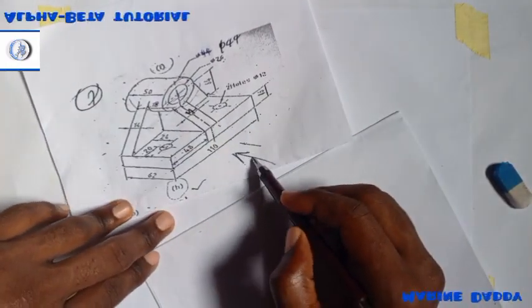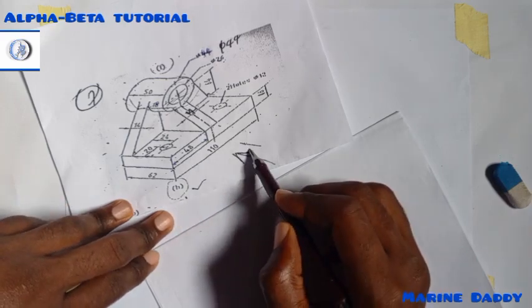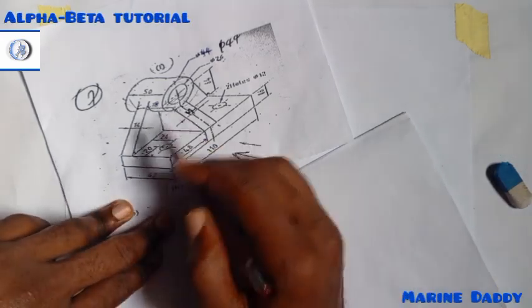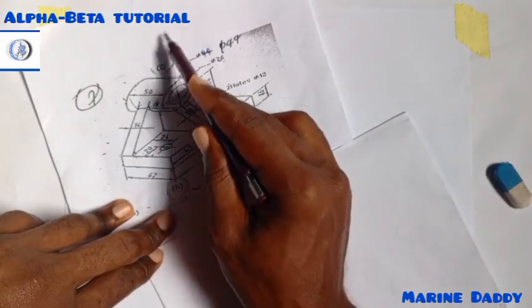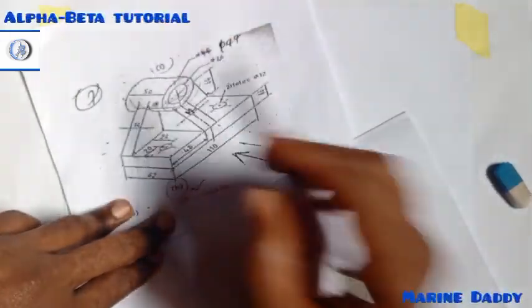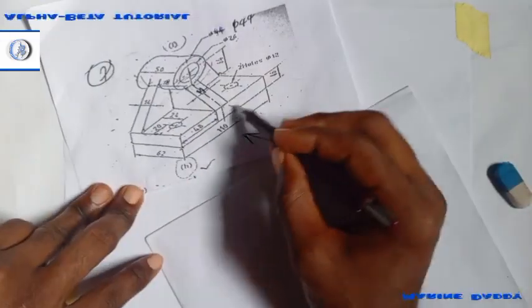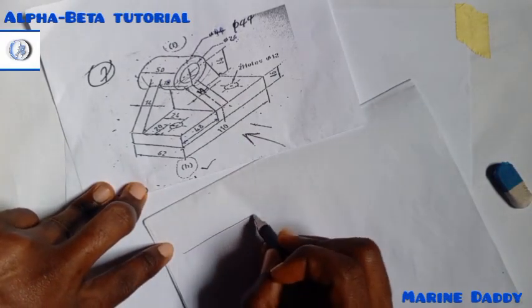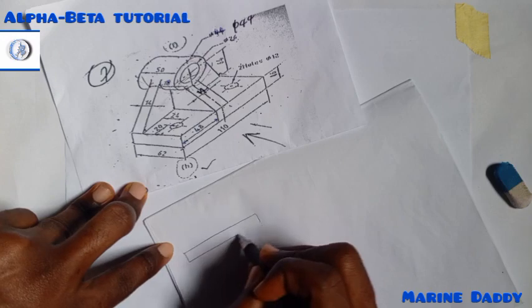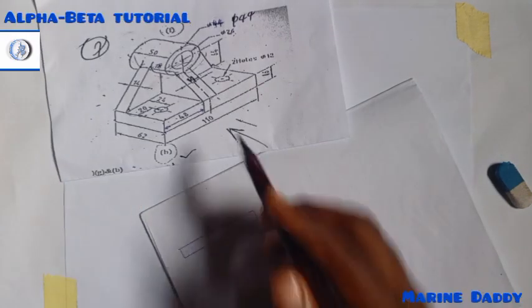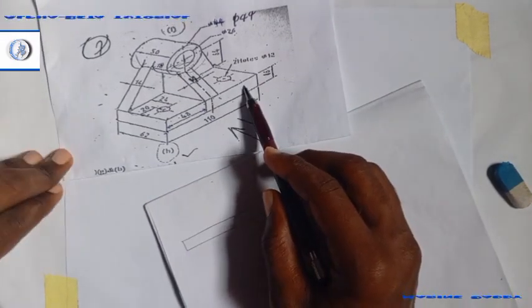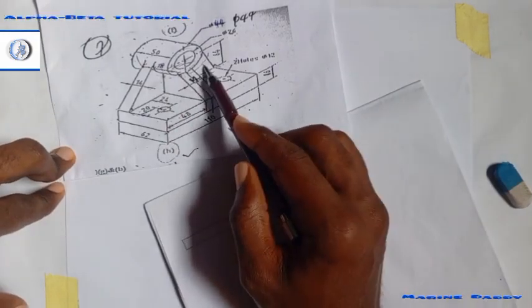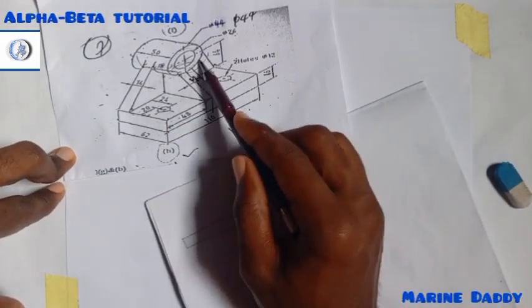This is our front view because of this arrow, right? So this will now end up becoming our side view, and here obviously becomes our plan from this top. So from our front view we can see this part of the diagram, so I will indicate it here. Putting it here, I can see this side, then I'll be able to see this side and this side clearly.